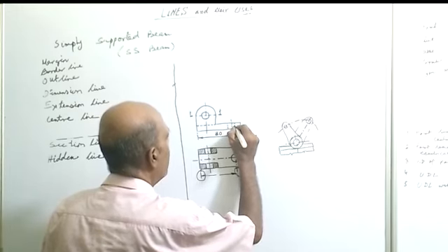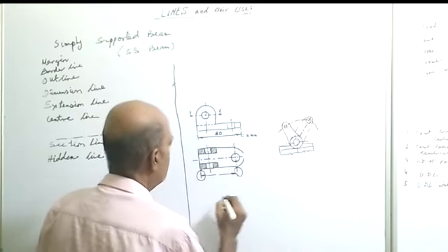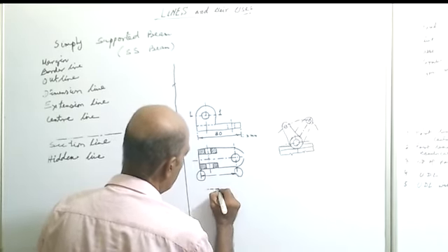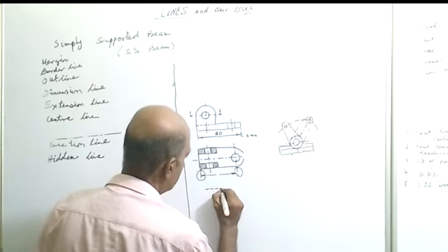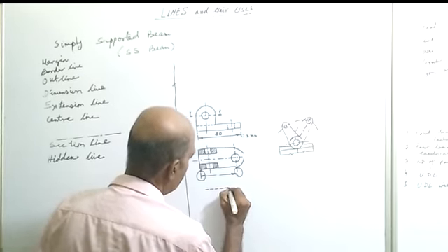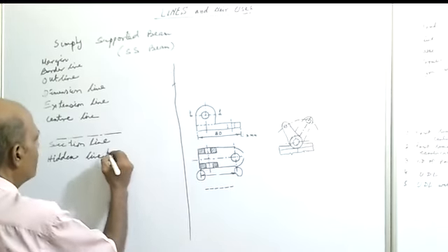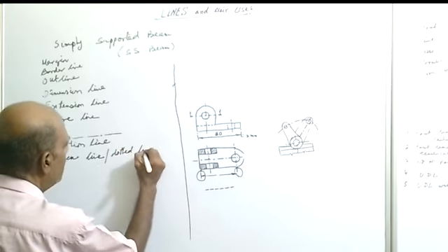This line is 2 to 3 millimeter long, then leaving a 1 to 2 millimeter gap, and it continues like this. The length in between remains the same, with a gap left between them. This is called the hidden line, or sometimes it is called the dotted line.